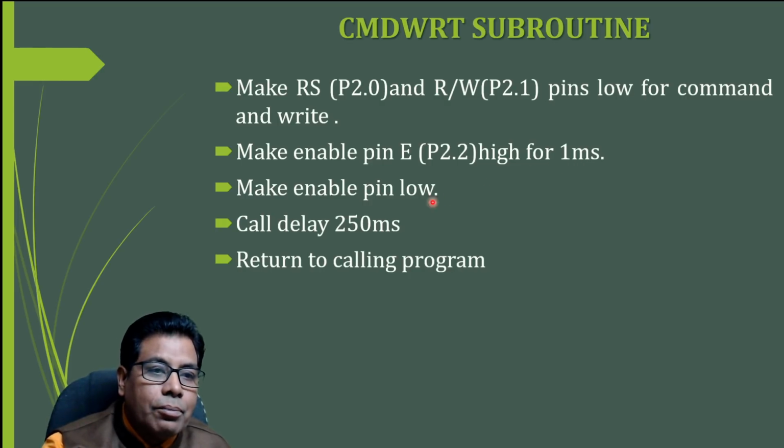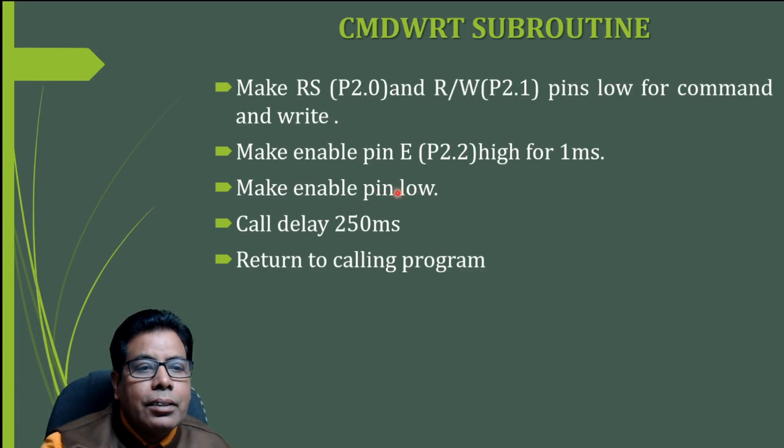Once we make the pin low, the transition from high to low will occur and the command will be latched in the LCD. Then we call a delay of 250 milliseconds because the LCD will not accept any command immediately. Then return to the calling program. So this is a subroutine, so it will go back to the main program.